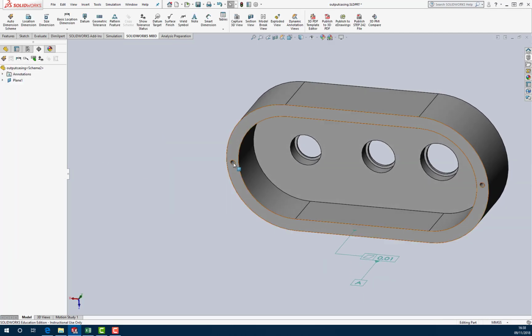We've got two dowel holes. So let's specify something about their size. They're going to be undersized relative to the pin, because we want an interference fit. And if we remember what we did with the pins that are going in there, they're on M6 tolerance. So if I recall, that's between about 4 and 12 microns oversized. So if this is an aluminium housing, you want 15 to 20 microns of interference on that.